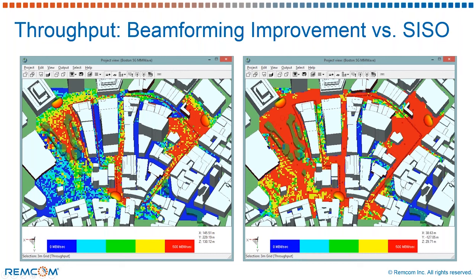Here we show the throughput along the route that we showed on the previous slide, and we can see that the single user MIMO technique, compared to the SISO baseline in blue, has been able to significantly increase the throughput, and over much of the route it's achieving its max 256 QAM throughput of just under 500 megabits per second. The dropouts have also been suppressed, and in the lowest regions, the worst dropout in this single user MIMO case is 142 megabits per second.